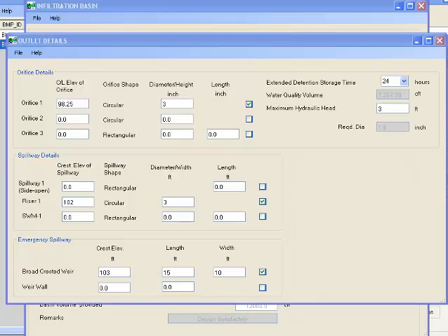The program uses the DCR method to average hydraulic head, which is the VDOT preferred method given in the Virginia Stormwater Management Handbook, and gives the size of orifice in inches. This size is used in the orifice sizing to the left of this form. There are 3 types of orifices for the user to choose from. 2 circular shapes and 1 rectangular shape are given.